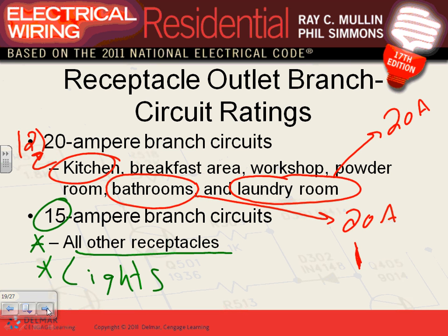I can't emphasize this enough, because you guys are going to be laying out your receptacles and circuiting right now. The question becomes: how many lights? Anybody come up with how many lights I'm going to put in the circuit, Chad? Now, I know here in the bathroom it's easy. It's going to be only one receptacle. By the way, the bathroom is an exception. You can feed the light in the bathroom from the circuit that feeds the receptacle in the bathroom. It's okay. In the kitchen, I can't feed the light from the same 20 amp circuits, excluded.